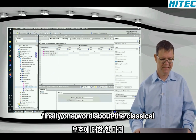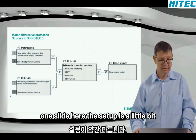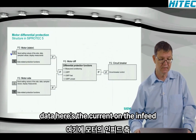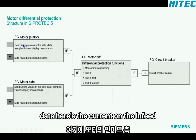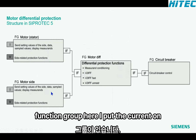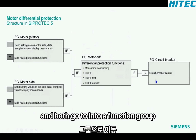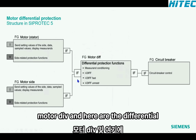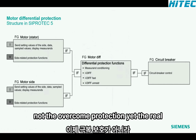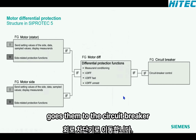Finally, one word about the classical differential protection. I've prepared one slide. Here, the setup is a little bit different. I have a function group motor stator. Here's the current on the in-feed side of the motor, and I have a motor side function group. Here I put the current on the start point side. And both go into a function group motor diff. And here are the differential protection functions, the real differential protection functions now, not the overcurrent protection. Here the real differential functions running, and this goes then to the circuit breaker.